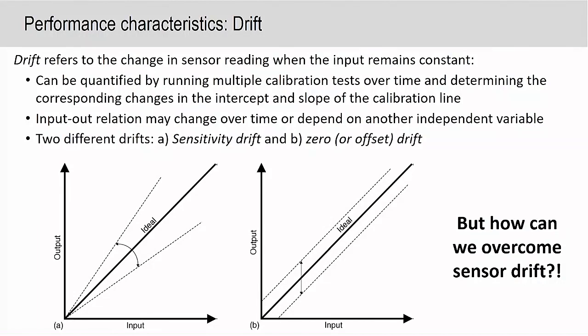We have implantable devices and non-implantable devices. For non-implantable devices, it can be a little bit easier because, as we showed before, you can calibrate a sensor. If we notice some drift, we can take a real value and recalibrate it. Not so useful if you're about to put this into a patient. You probably don't have time to be sitting there calibrating a sensor. But it's particularly bad if it's inside a patient.